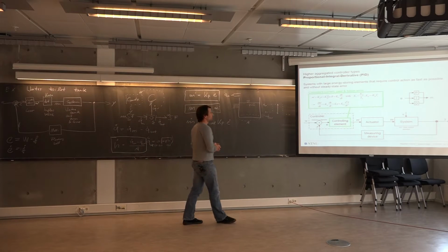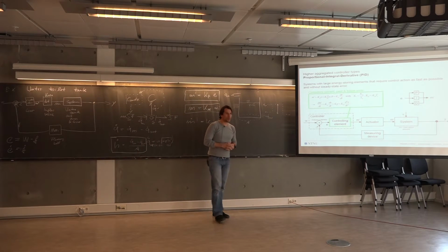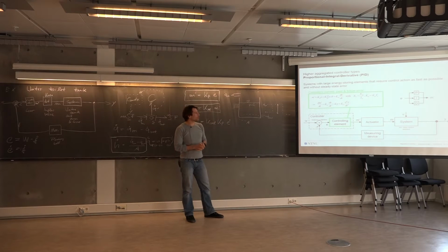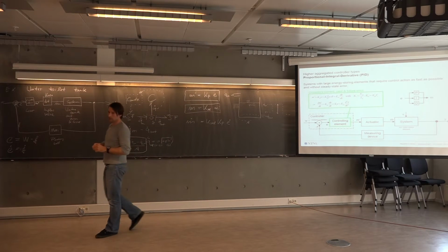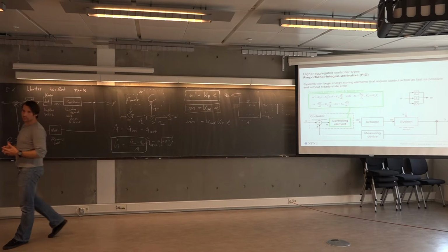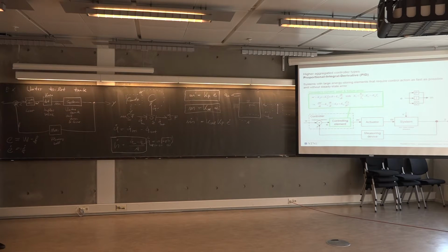It is especially important when you have systems with large energy storage elements and you need a fast and high dynamic response of the controller, and due to the integral part, something without a steady state error, right? Where you want to get rid of this steady state error totally. So it combines all the positive elements of the single controller types